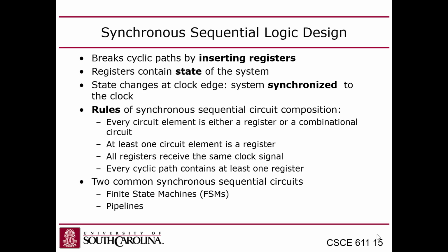So that's a problem that you might encounter in this class. You have to be careful that if you have a cycle where a signal could affect the evaluation of that same signal, there needs to be a flip-flop in there that interrupts that cycle. So that's what they're talking about there.